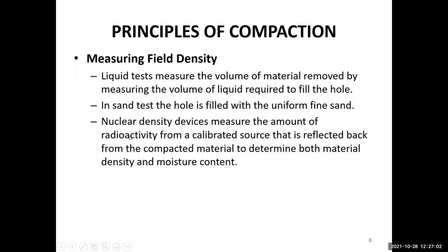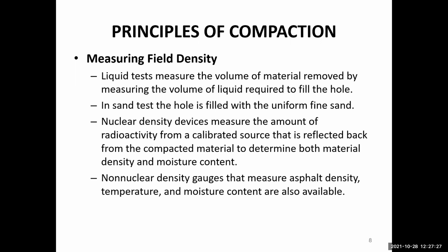More sophisticated methods use nuclear density devices. These nuclear density devices measure the amount of radioactivity from a calibrated source that is reflected back from the compacted material to determine both material density and moisture content. So this type of calibrated equipment gives us the measure of the density.